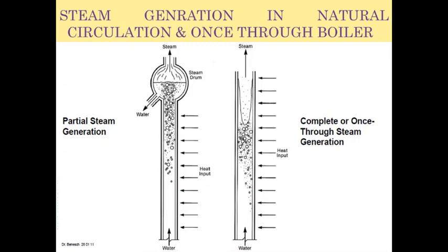In case of an open system, when we go on adding heat, the water coming inside the flow passage is receiving the heat and gradually there is a rise in temperature, and once the amount of heat received takes the water to the saturation temperature, gradually latent heat of vaporization is getting added.